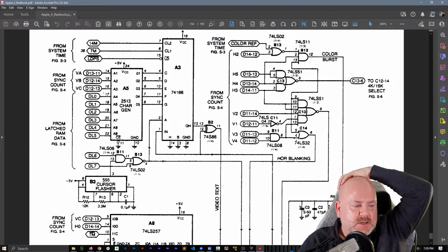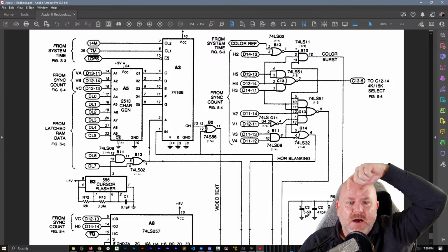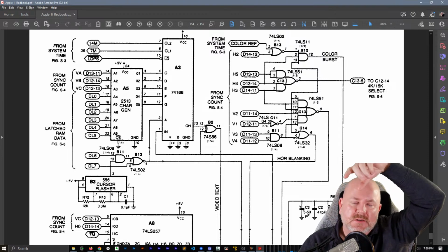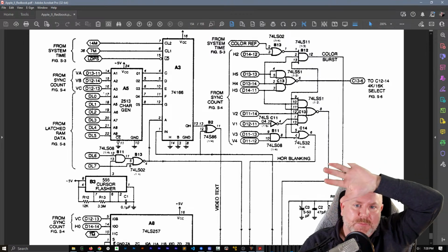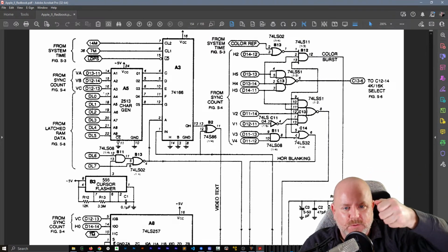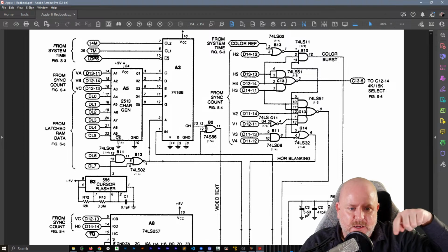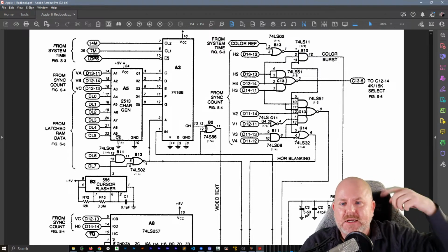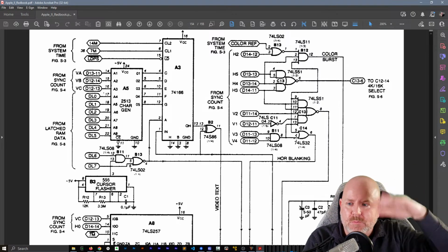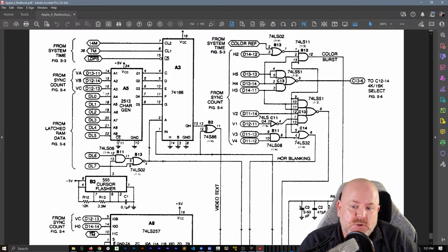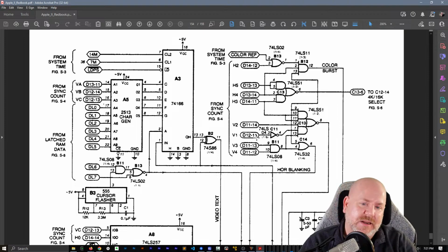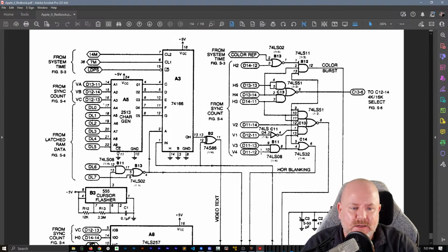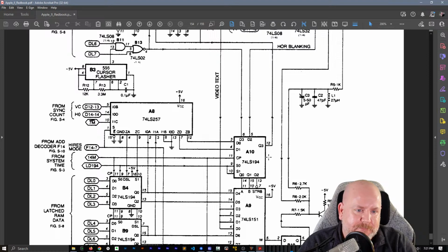If you're doing a design that had some ICs on it, you could either do SOICs, and if that's too small for you, then put sockets and tape the sockets on the top side, turn the board over, and then solder all your sockets, but then have all the pads for your decoupling capacitors. That way you only have to turn the board over one time, and it's super easy. And 1206 capacitors are easy to find.